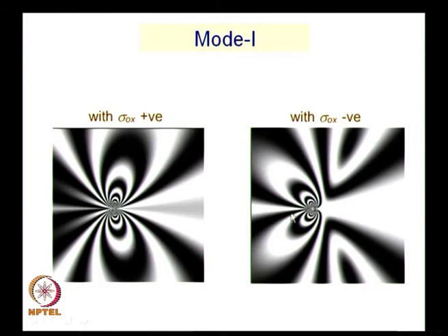So, here I have cracks tilted backward, and this kind of situation is seen in the case of a different type of specimen known as the rectangular double cantilever beam specimen. We have already looked at the double cantilever beam, where we had very thin top and bottom portions.